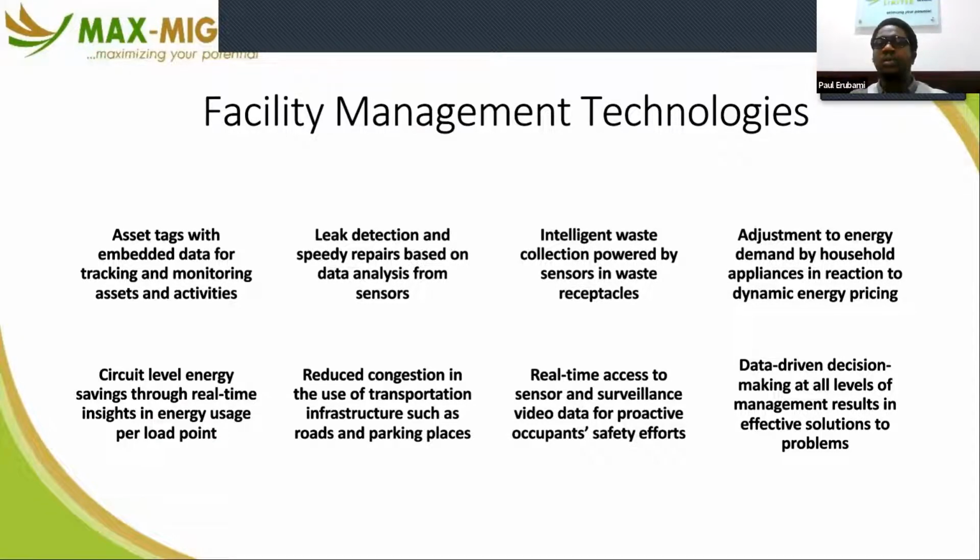So those who must have things at peak period will have it there and pay the 15 naira. And most other things would have moved to the night hours of 10 naira. So the power plant will run at the same size of equipment and capacity, and then have probably the same 70, 80 during the day and 70, 80 during the night, right? Otherwise, they would have had so much for the day and very little at night, wasting so much capacity. So that's what dynamic energy pricing is.